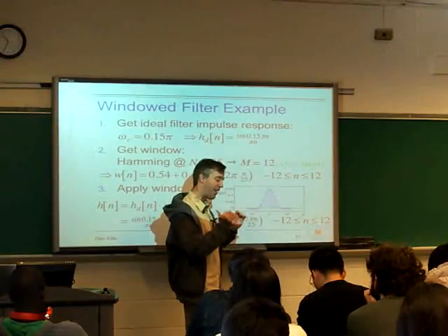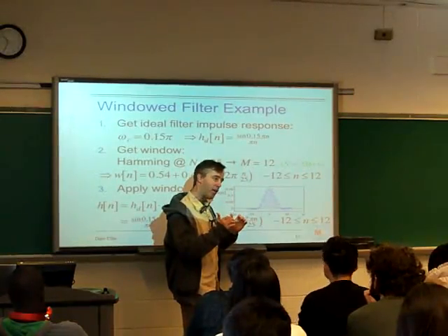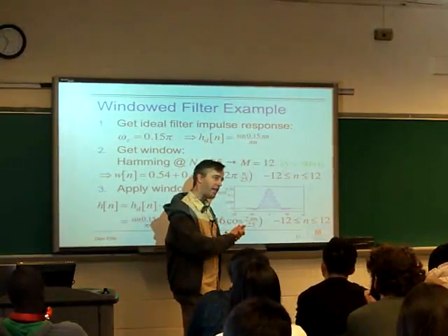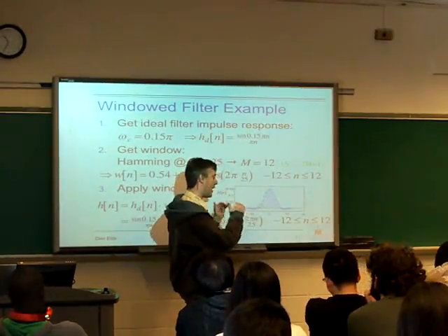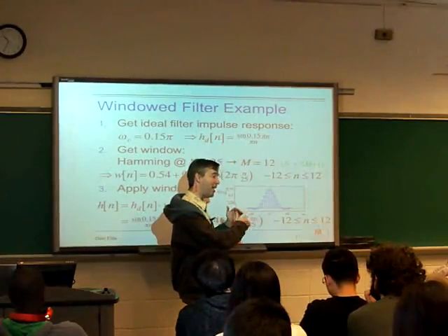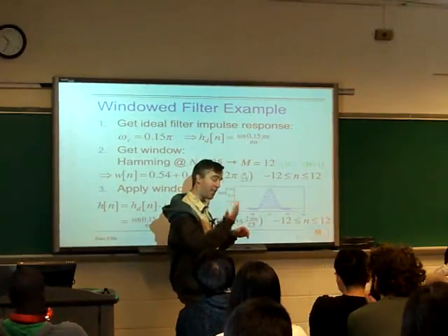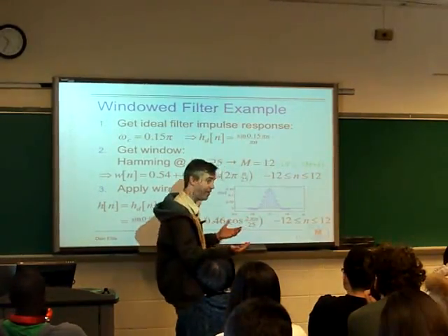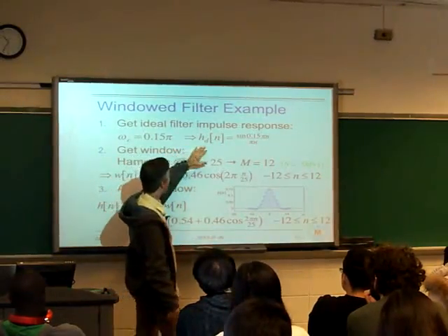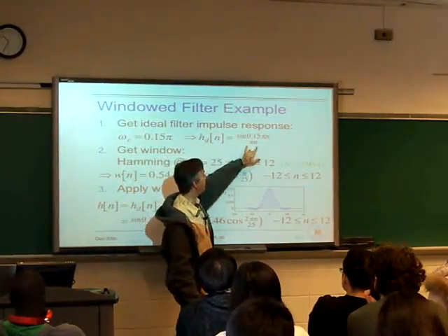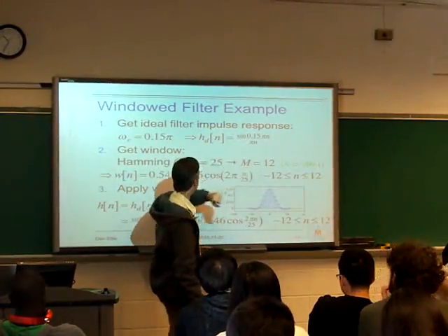When the rectangular thing is in the frequency domain, we're doing the IDTFT, which means we get a sinc function, sin x on x. When the rectangular function was in the time domain, we're doing the forward DTFT, which has to be periodic, so we get the periodic sinc, sin nx on sin x. But this is converting from the frequency domain to the time domain, so we get an infinite duration sinc function like this.